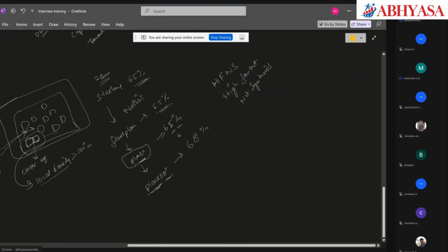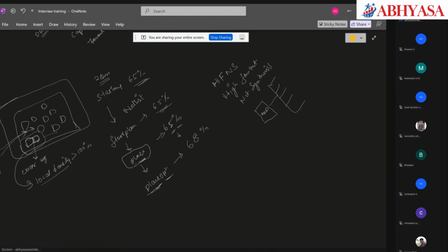Simple. In high fan out net synthesis, let's say my AND gate is connected to 15 other gates. What HFNS will do is add buffers, building a buffer tree in such a way that the load of the AND gate will reduce. I had 15 as the fan out of the AND gate.